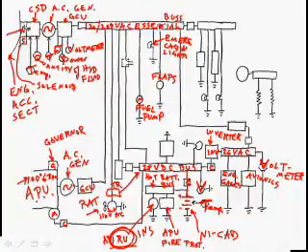If we've got this 128 volt AC bus, if we follow this right down here, this could be a transformer rectifier through a contactor, so that we can use the step-down transformer to reduce the high voltage to low voltage AC, and then use the rectifier to convert the low voltage AC into low voltage DC. So under normal conditions, we're going to power the 28 volt DC bus off of the essential bus, and of course now it is going to be a higher voltage than the battery, so it'll charge the battery, and of course it'll feed and power the hot battery bus, so the battery won't discharge.